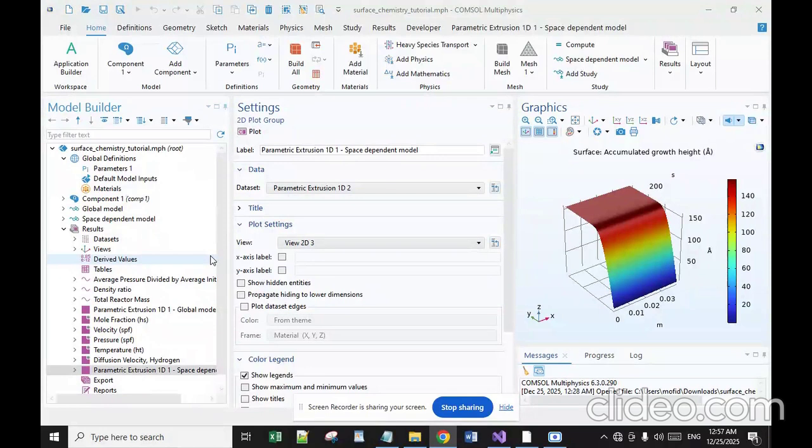In addition, silicon oxide alloyed with phosphorus pentoxide, or P-glass, can be used to smooth out uneven surfaces. P-glass softens and reflows at temperatures above 1000 degrees centigrade. This process requires a phosphorus concentration of at least 6%, but concentrations above 8% can corrode aluminum. Phosphorus is deposited from phosphine gas and oxygen.